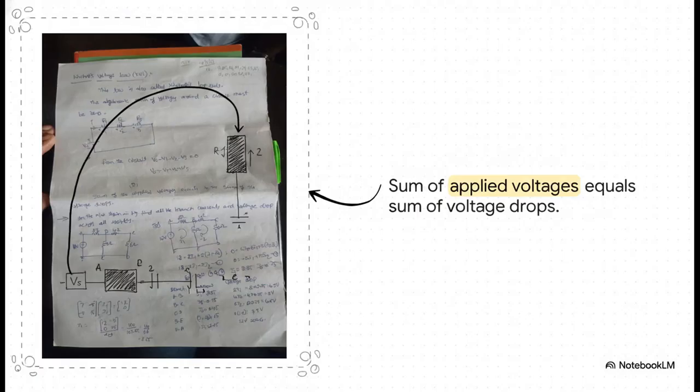This sketch right here is a gorgeous example of KVL in action. We've got a voltage source, Vs, pushing energy into the loop, and 3 resistors, R1, R2, R3, taking little bites of that energy out, creating drops, V1, V2, and V3. KVL mathematically proves that the energy supplied perfectly matches the energy consumed. Vs just equals V1 plus V2 plus V3. It's a perfect closed loop of energy.